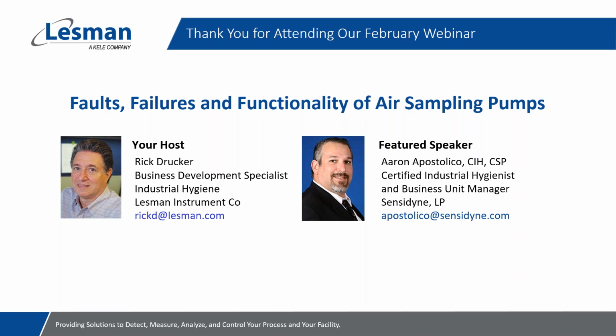Next question, is 5% always the standard allowable flow deviation in ambient air test methods? I would say that's the general standard in industrial hygiene. What we typically want to see is that your starting flow rate and your ending flow rate are less than 5% apart. So if you were to calibrate your pump at 1 liter per minute, we would want to make sure that your ending flow rate was within plus or minus 5%. That really goes to the integrity of your sample: when you start deviating more than that 5%, your ability to rely on that concentration and results starts to really deviate.